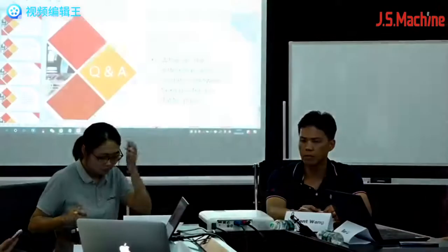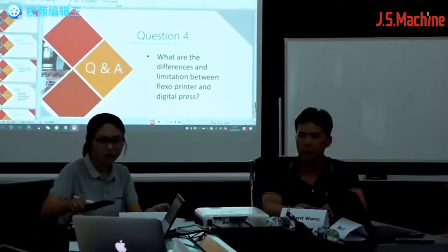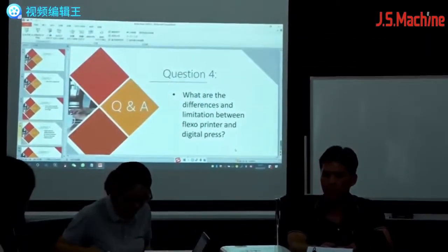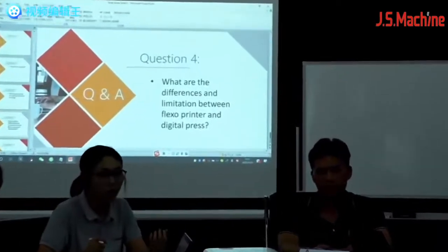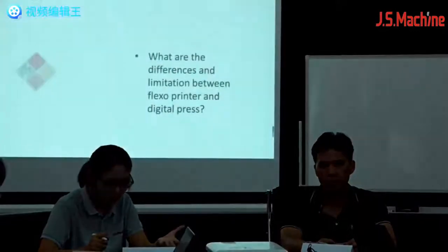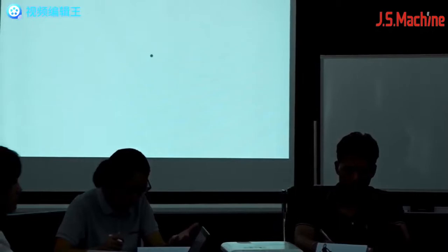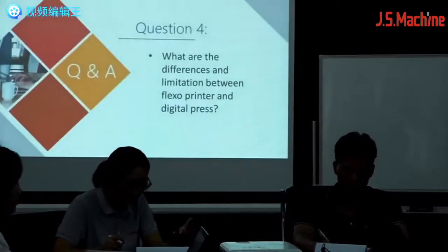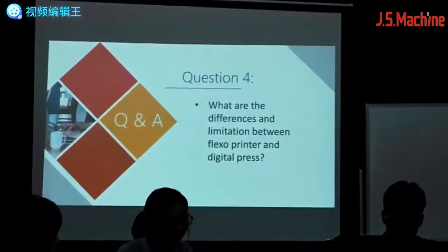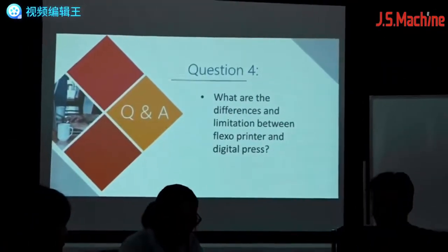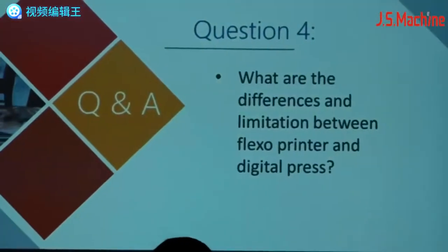The answer is that currently the merit and advantage of digital printing is that it has a much quicker time during the order change. Usually it costs about 1 or 2 minutes for the order change. And it doesn't need a printing plate, as I mentioned earlier, so it is flexible and rich in pattern design and also in packaging design.